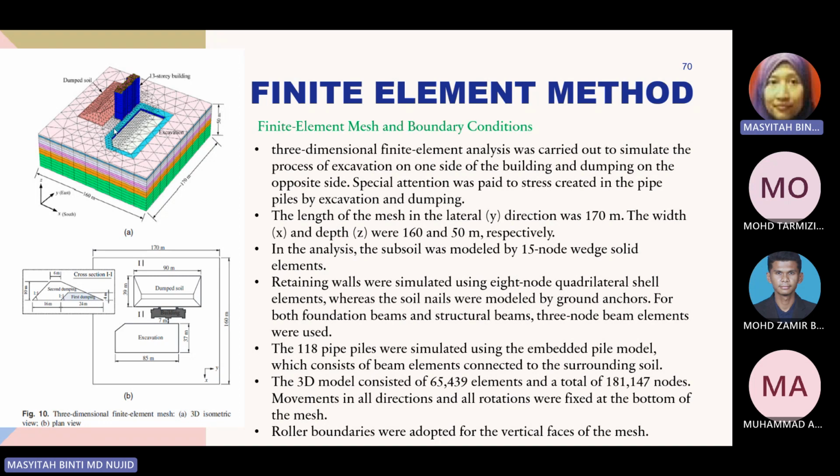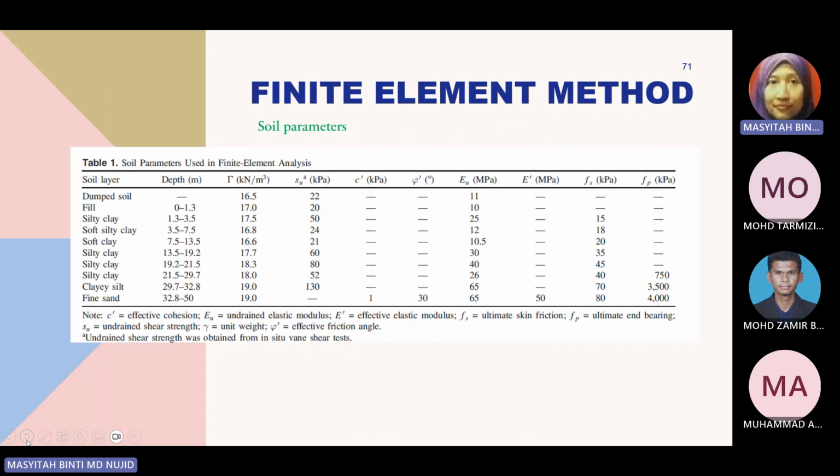If you are focusing on the soil layer, we use a very fine mesh. If you ignore the effect a few meters below the ground surface, we can have a coarse mesh. That will give different answers for displacement, for example, and also for deformation.